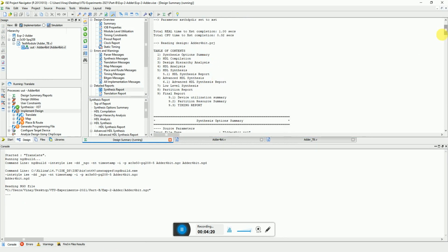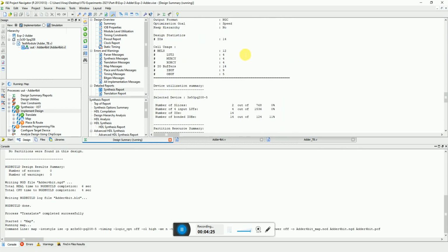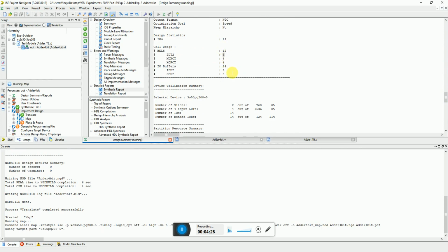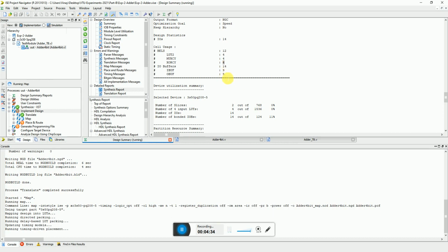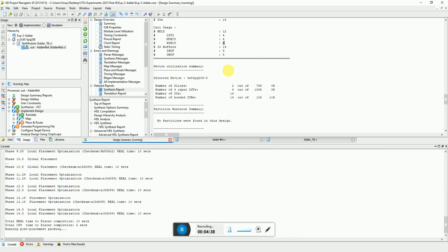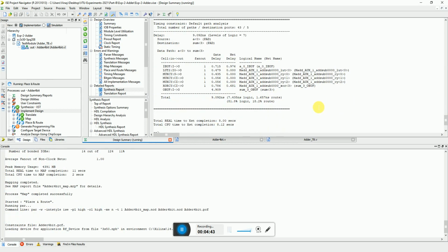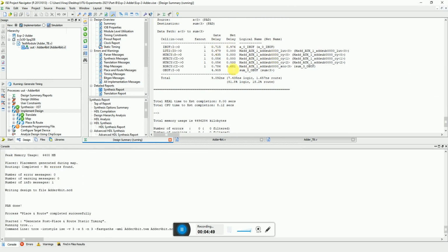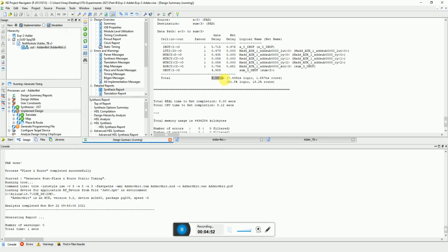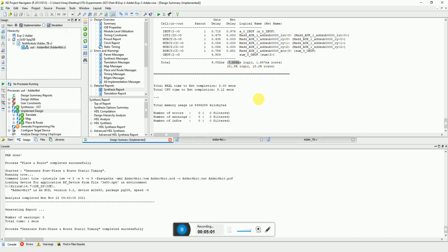If you want, you can see the detailed synthesis report, so you can go inside and see what is happening. Here you can see how many lookup tables have been used, how many XOR with carry are being used, how many input buffers have been used. If you see any discrepancy, you can notify it in your design and make changes accordingly. Here are the delays of each and every input buffer. Out of which 7 nanosecond is for logic, 1.65 is for routing. That is how you can get bifurcated timing delays.